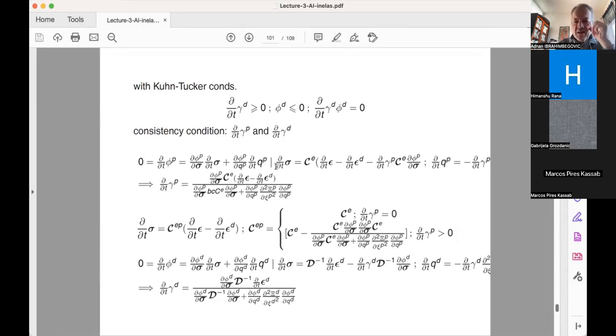And basically from this equation we can easily obtain, if you keep linear isotropic hardening, we saw that it's only a single linear equation. You get your plastic multiplier to be equal to the derivative of d phi plastic d sigma times C elastic times epsilon dot minus epsilon damage dot, divided by d phi plastic d sigma, the elasticity tensor CE times d phi plastic d sigma, and here would be d phi plastic dq times the hardening modulus K plastic times d phi plastic dq.